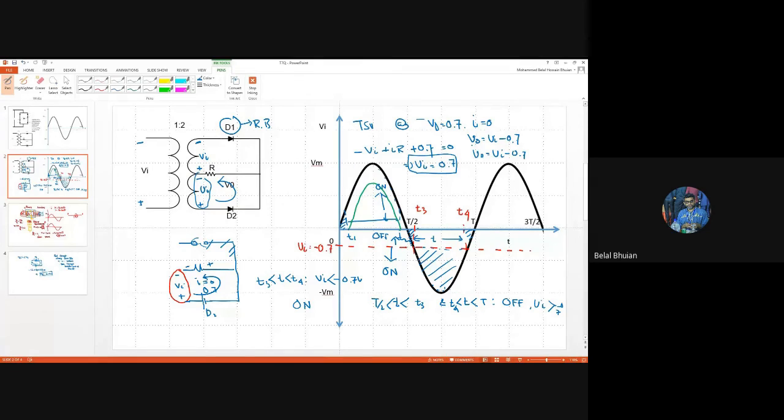Now this is only the magnitude, this is also the magnitude. So even though we are considering the negative half cycle, the value of V naught we got is positive. We are going to put the magnitude only. So if I draw it again, 0 here, 0 here, and for the output it will look like this, for when the diode is on. So for the positive half cycle it has been rectified, and for the negative half cycle as well. Although its input signal is negative, its corresponding output signal is flipped.